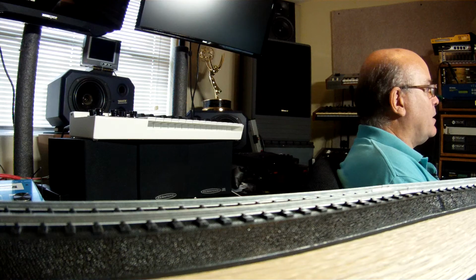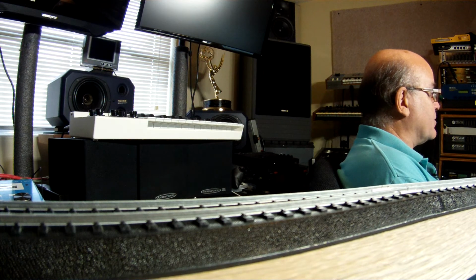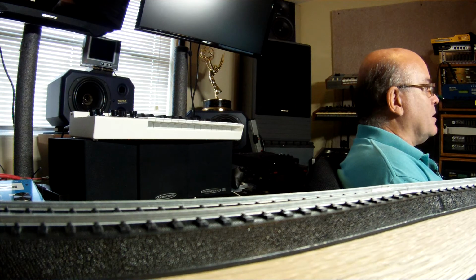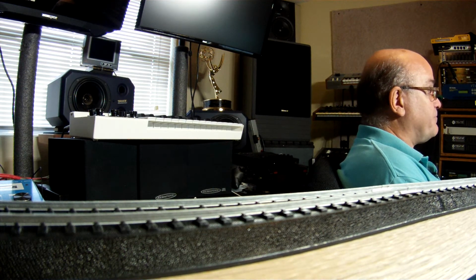Whereas with a softer or shallower filter slope like a first order filter, there's a lot of overlap, so you wind up with a lot of low frequency information going to the horn component and a lot of high frequency information still going to the low frequency component. Inexpensive electronic crossovers are typically 12 dB to 18 dB per octave units, while better quality units are typically 24 to 30 dB per octave, which means a fourth or fifth order crossover, and really expensive ones are 36 dB per octave, which is fairly extreme.